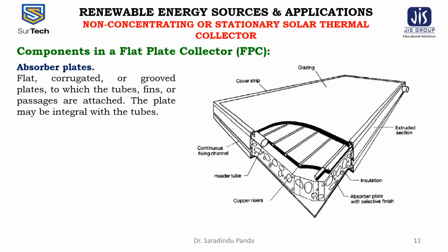The absorbance of the collector surface for shortwave solar radiation depends on the nature and color of the coating and on the incident angle. Usually, the black color is used. However, various color coatings have been used for the aesthetic sense. By suitable electrolytic or chemical treatments, the surfaces can be produced with high values of solar radiation absorbance, alpha, and low values of the long wave emittance, that is epsilon.